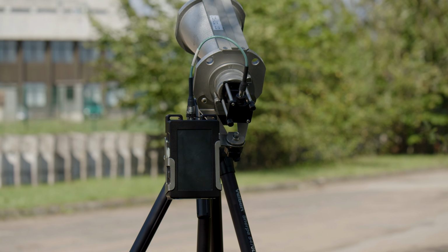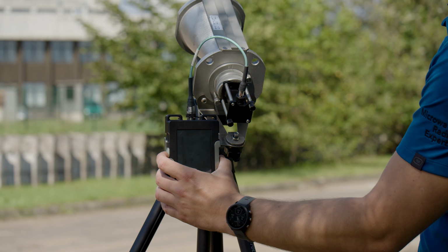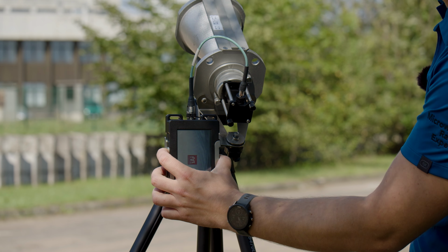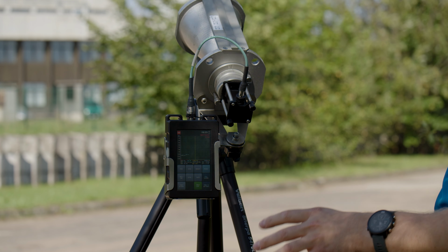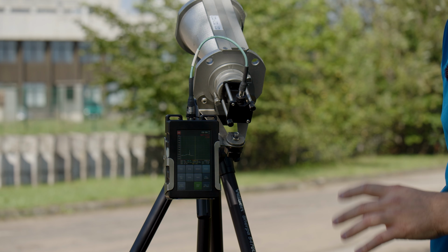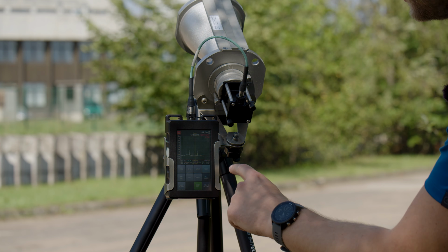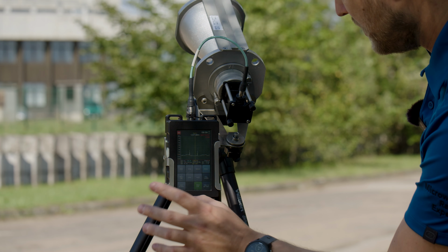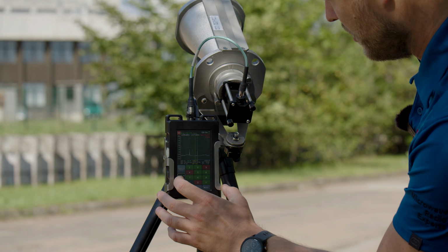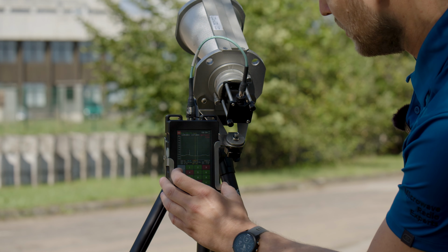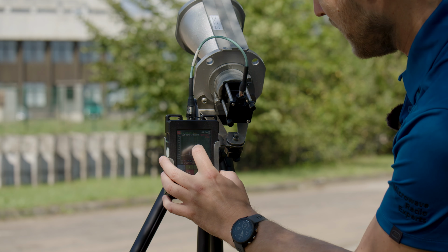Okay, so when we have the measurement setup ready, we start by obviously turning on the device. A really important feature of the Spectrum Compact is that once you turn it on, in a matter of seconds it's ready to do the measurements. This is very handy while we are in the field. Currently we are doing the full sweep from 6 GHz to 20 GHz, and we see two obvious signals appearing, but we know that the signal of our interest is around 14 GHz. So we will set the marker onto that signal.